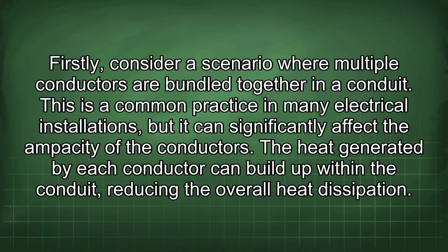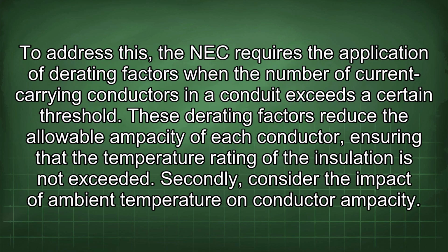The heat generated by each conductor can build up within the conduit, reducing the overall heat dissipation. To address this, the NEC requires the application of derating factors when the number of current-carrying conductors in a conduit exceeds a certain threshold. These derating factors reduce the allowable ampacity of each conductor, ensuring that the temperature rating of the insulation is not exceeded.